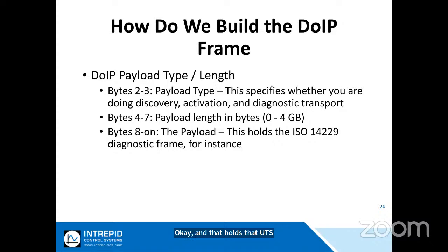Or that payload might be the data that we're flashing, because we could be doing ISO 15765-2 as part of 14229. And that is referenced, like many of the things we talk about. There's a reference at the end that's a full page of all the other ISO specs and other specs it draws from for DoIP.